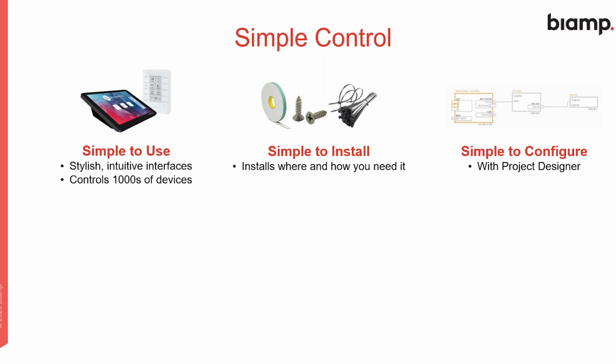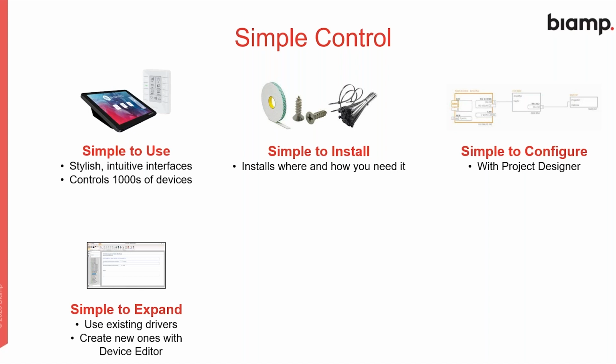Simple to configure. We have one piece of software called Project Designer, which is where you load in the controllers you want to use and then also the products you want to control. And then you integrate those in terms of how the functions or the functionality will interface with the user controls that you also give. If by chance we don't have the driver for a product you're trying to use or control, we have another piece of software called Device Editor, which allows you to make your own drivers to be used inside Project Designer. So long as you know the API for the product, it's a simple task to make your own driver and add it into your own personal library of products.